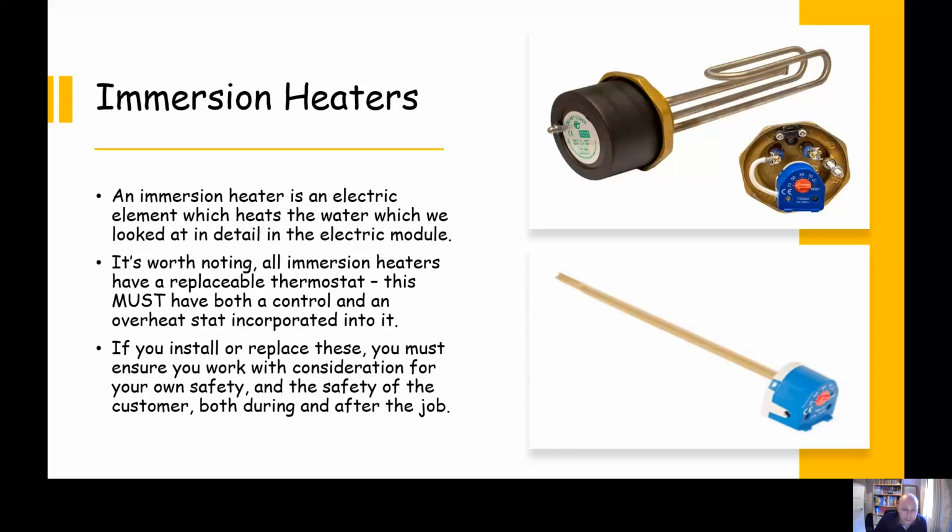And important to note, all thermostats in immersion heaters must have a control stat and also a high limit stat. The high limit stat's there to essentially make sure that the water doesn't boil in the cylinder.